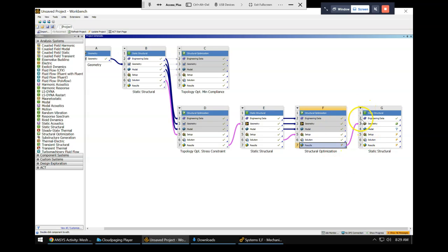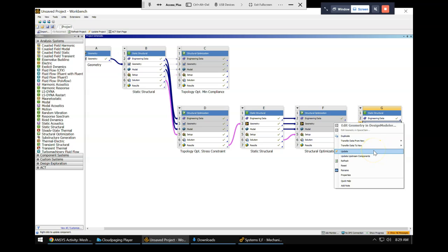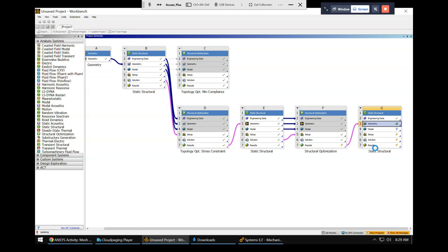When that happens, you'll get this new static structural block. That'll be our verification run, analogous to this previous one we had here. So what we're going to do is right-click on that geometry there, and just do update. Even though it's created that block, it still needs this update step to tie it in. So what we did was right-click results, design validation system geometry. And then once that static structural popped up, we just right-click geometry and said update. That takes a little bit. I'm not sure what the distinction between those two steps is. Seems like it should just be one step.